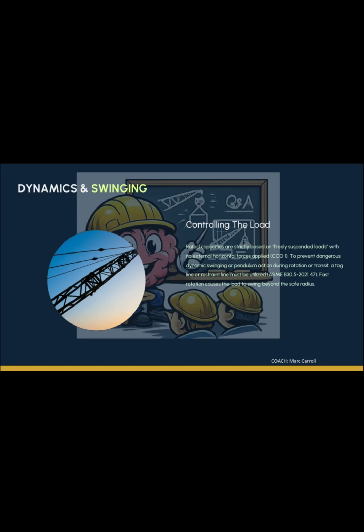If extra wire rope is reeved beyond the minimum required, the operator must deduct 1 pound for each extra foot. Not negotiable. The TLL load charts deduct for excessive rope. Don't forget this.